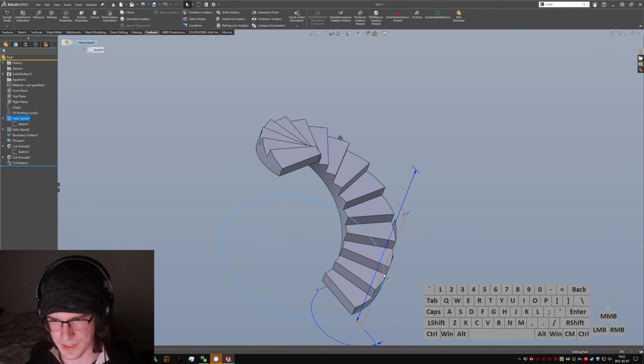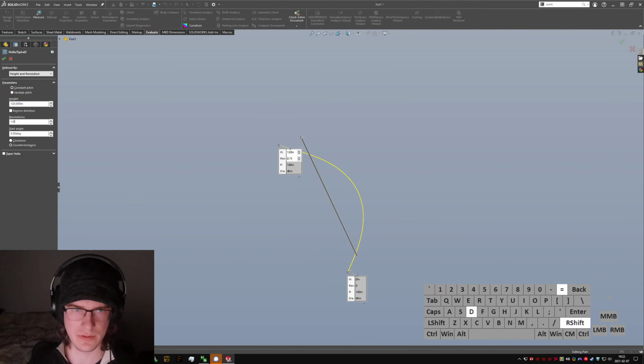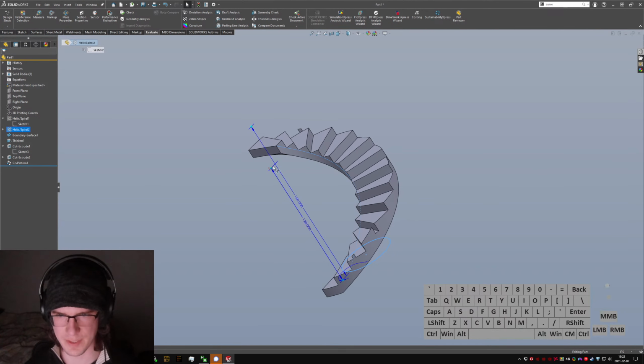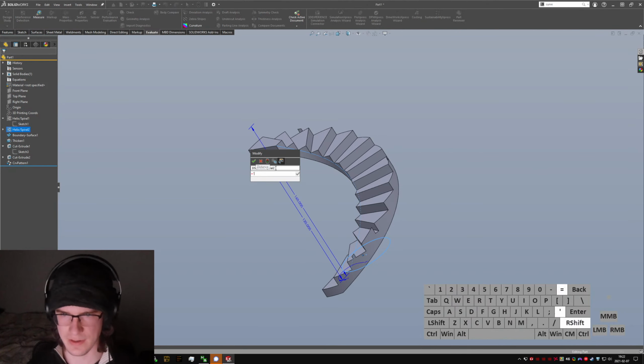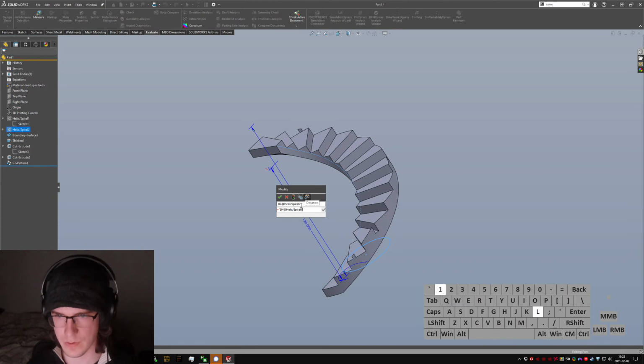Let's see, what does it say? There should be a dimension around here that we can grab. Here we go. D5 at helix spiral 1. So now we can come to helix spiral 2 and make this one equal to D5 at helix spiral 1. Maybe I have to select the dimension over here. Yeah. Oh, helix slash spiral. That's ridiculous. Equals D4 at helix spiral 1.